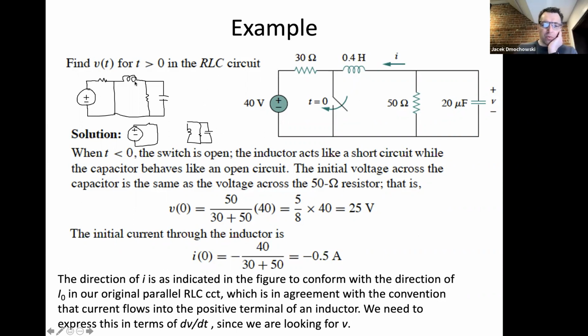Why? Well, consider any current that comes out of the battery and goes through the left resistor, right? All of it is going to come back here. It's not going to go through here because it has a short circuit path back to the battery. So the current from the battery is going to ignore everything over here. Similarly, let's say that magically some current appears through the inductor, right?